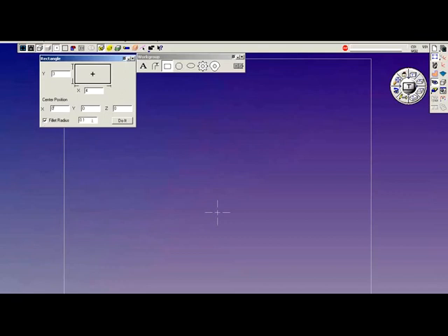If I select the fillet, type in 0.5 to make it nice and visible, do it. I can generate a rectangle or a box with fillet radii. Uncheck it, do it, and you get the square cornered box or rectangle.